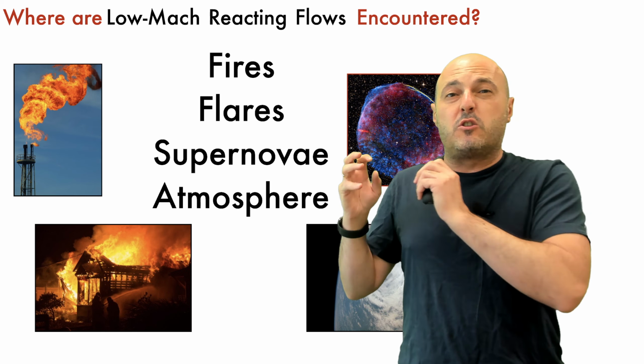But what matters the most to our discussion are two types of motion. What we call the bulk flow motion, or the advective motion, and the acoustic motion. These are sound waves, which allow sound to propagate. This is an actual imaging of a speaker done in the 50s showing how waves are propagating in the air.